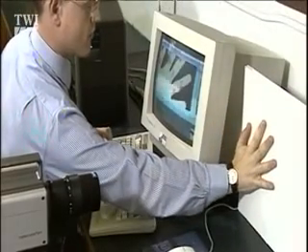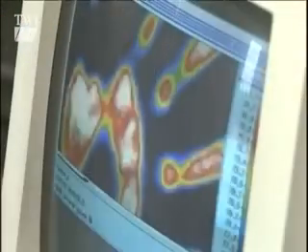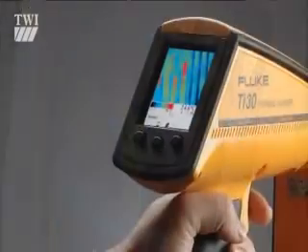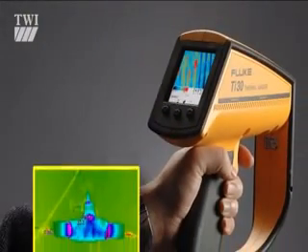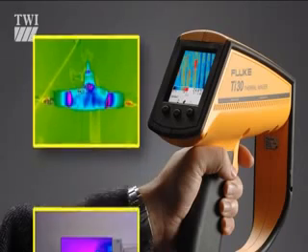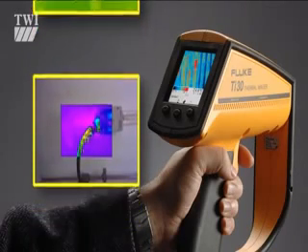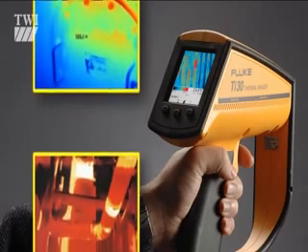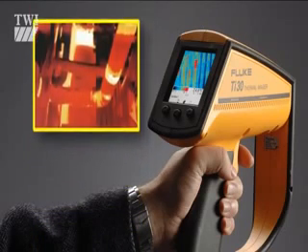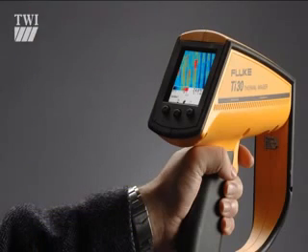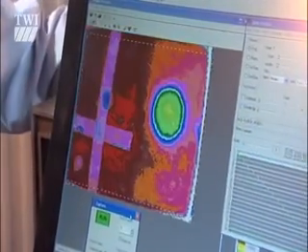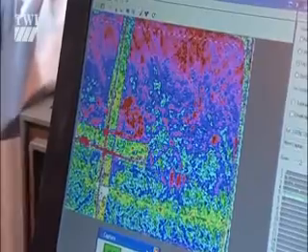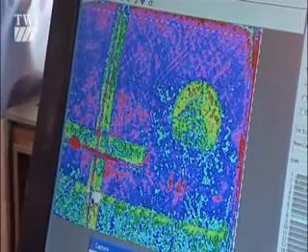Lastly, to thermography. Thermography is the simplest of all thermal inspection techniques. It involves using an infrared camera to look for abnormally hot or cold areas on a component operating under normal conditions. Most modern thermal cameras are able to detect temperature differences of less than 1/4 degree Celsius, and they enable thermal images to be recorded on video or computer disk for future analysis.